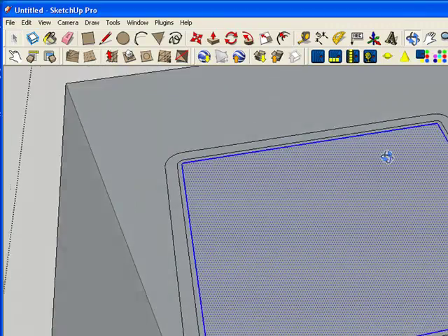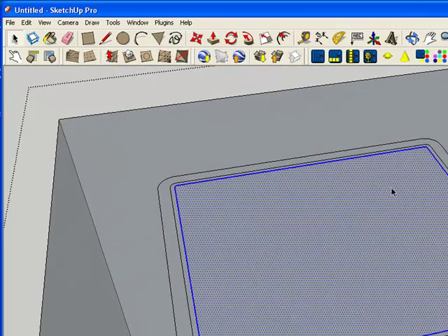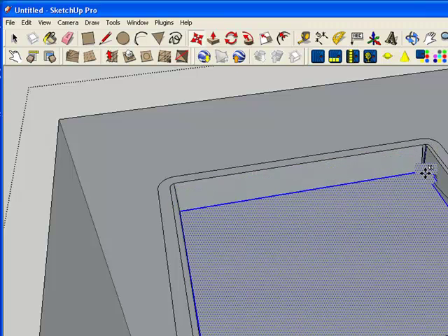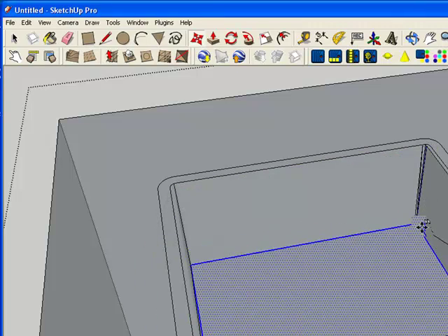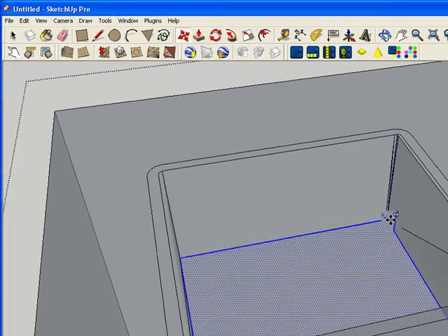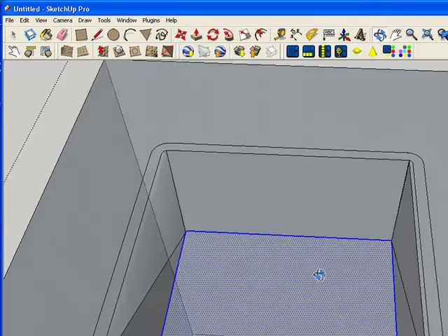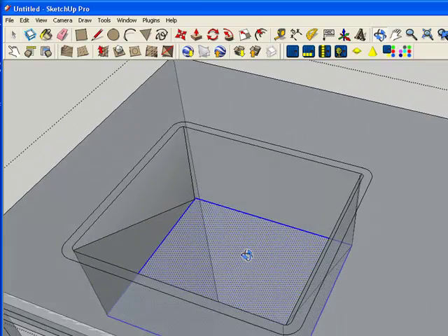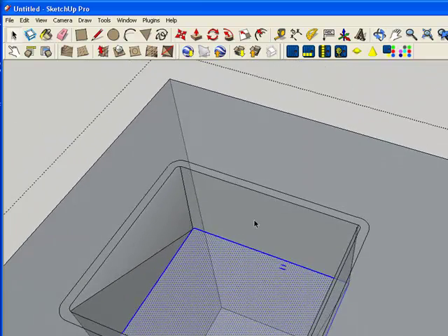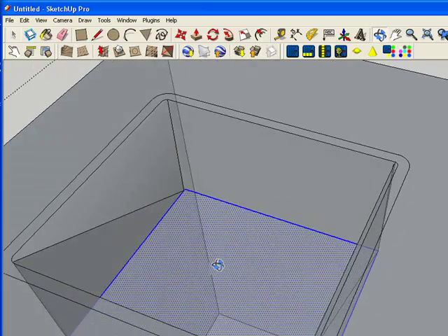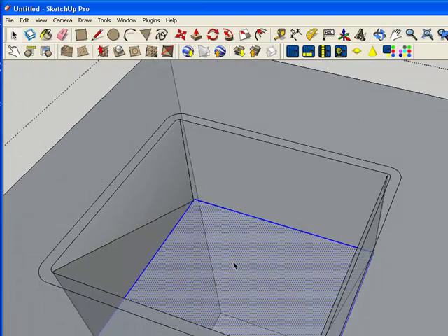What we do is then we highlight that, click on the Move tool, grab the corner, left click and hold, and then hit the Alt key. And if you slide right down, and it's a little tricky to get it going in the right direction. Okay, there it is. What happens is it's created the taper. So the inside of the sink is actually, bottom is narrower than the top of the sink, and you get the right function. So that's a really neat function that the tool has.